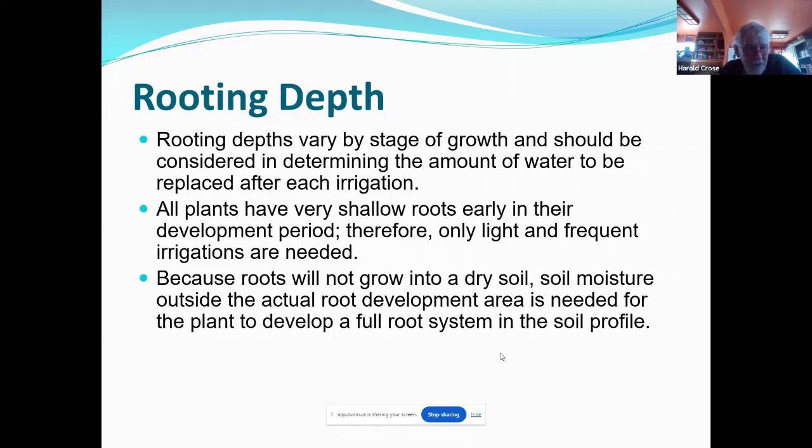And so basically that crop was in moisture deficit for the amount of growth it was a mature tree. So the reason I bring this up is that if you have a grower come in and want to convert from some of these types of systems to another, you better make sure that they're putting that system in to cover the original water pattern of that crop, or you can run into some real problems. So we doubled up on the emitters on that and moved some of them out away from the tree, and it took 3 years to bring the crop back to where it was initially.